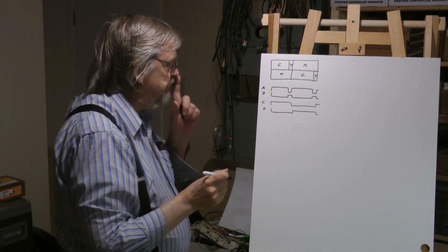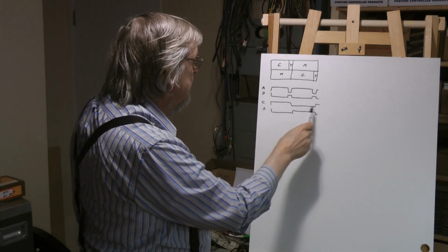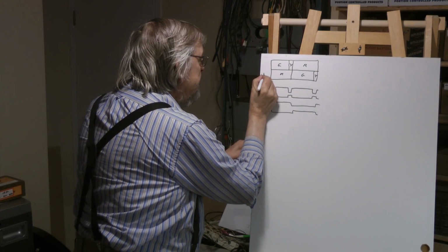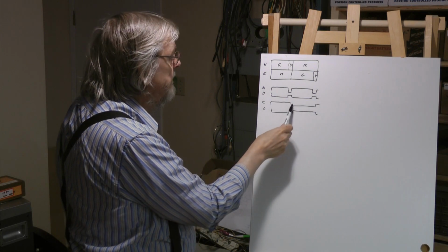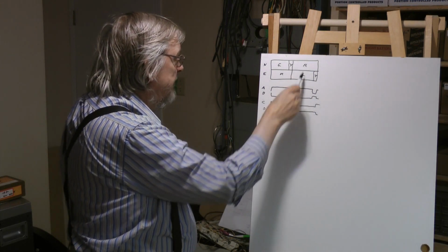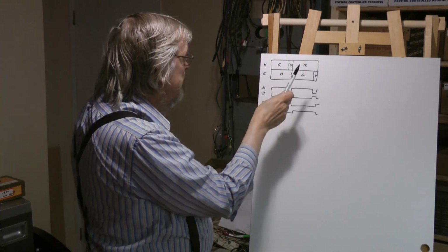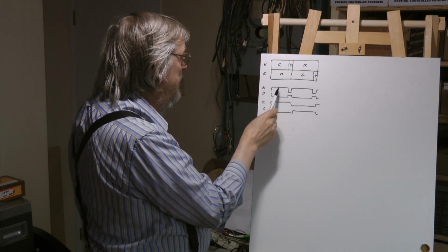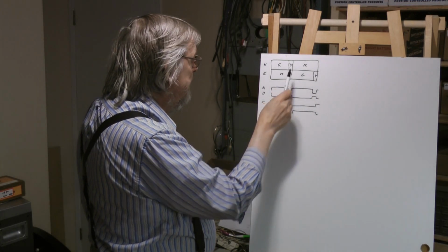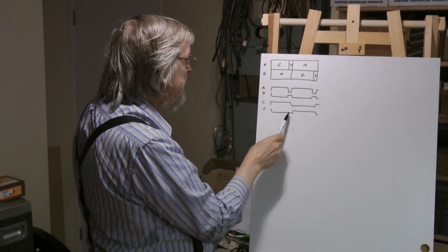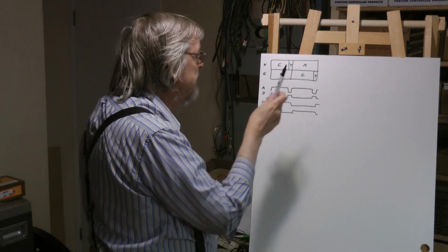C, and D. So for example, red would be all of this. Red on this side, let's say that's east, that's north. So east red would be waveform C. North red at this time would be waveform D, and so on. Now for green north, we would want A plus C, so we'll need an AND gate. Yellow north, we would want B and C. So a couple of AND gates, a couple of drivers.